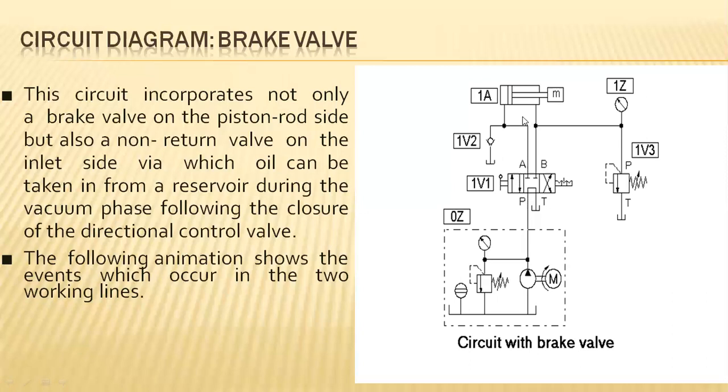This oil will be moving in the forward direction, which causes the pressure relief valve to maintain a nominal difference in pressure. For example, the entering pressure is 2 bar and the releasing pressure will be 1.9 bar, that is a 0.1 bar pressure difference. That 0.1 bar of extra pressure at the inlet creates the forward movement of the